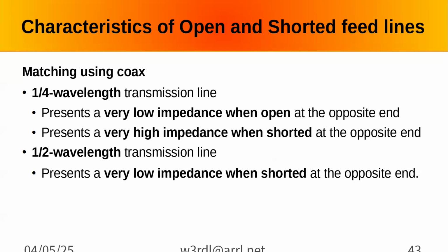Okay. If I have a piece of transmission line that's one wavelength long, and we look at it at 3 points, quarter wave, half wave, three-quarter wave, you're going to see that waveform on it, right? And it appears from an impedance standpoint to go from high to low to high to low as you go along the line.